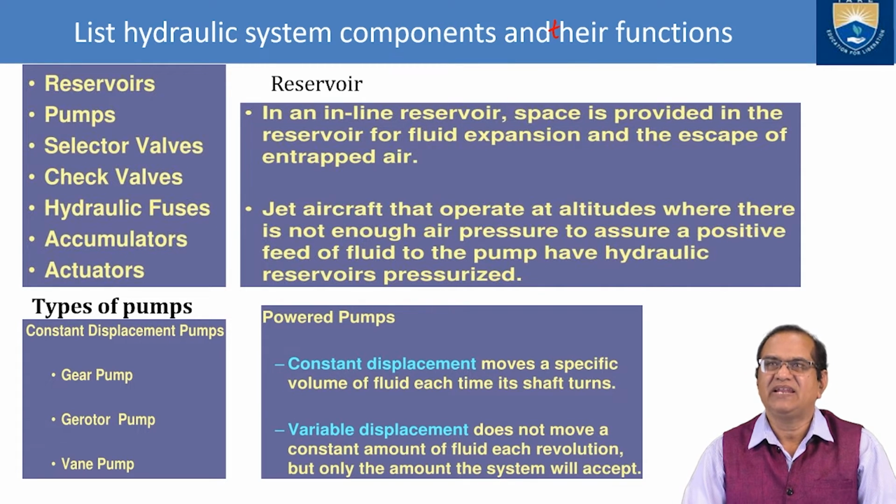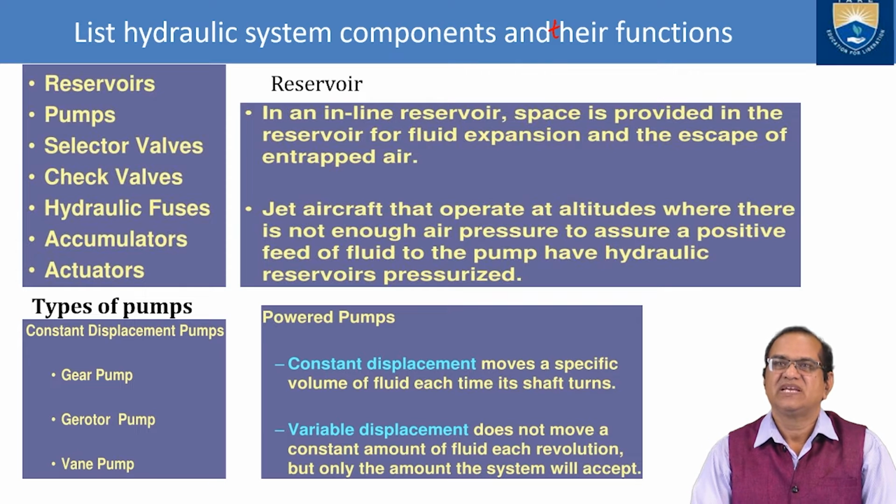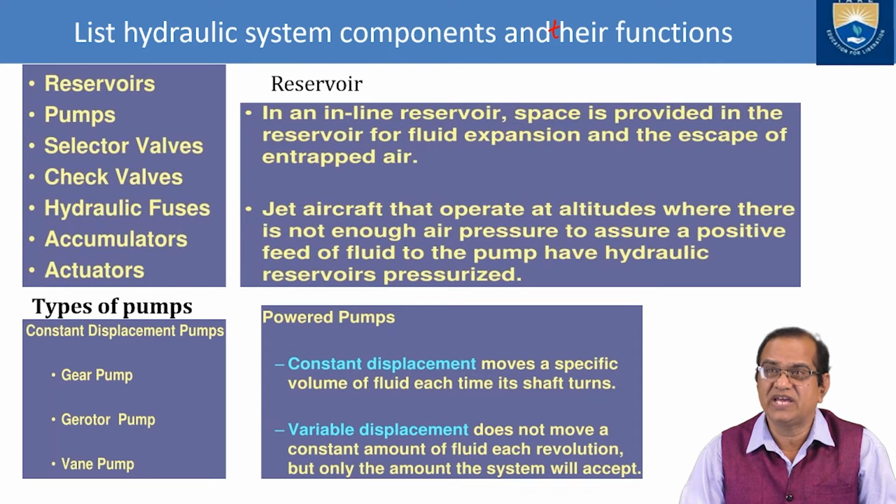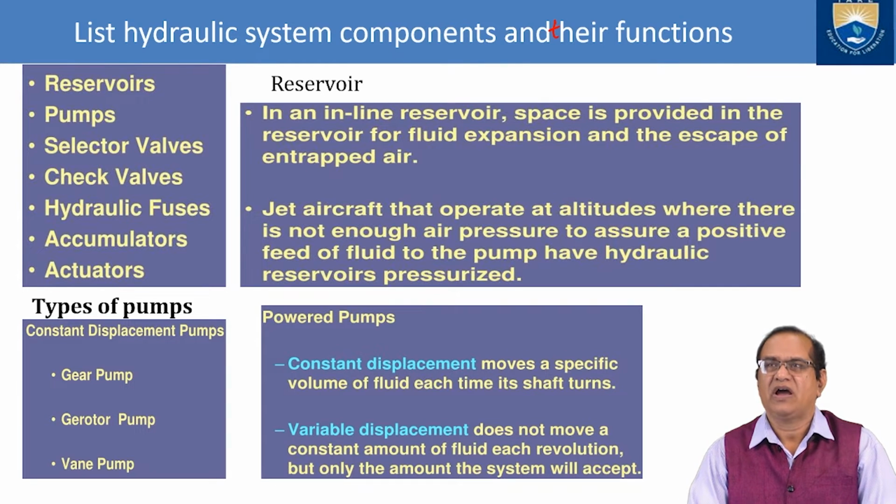In an inline reservoir, space is provided in the reservoir for fluid expansion and the escape of entrapped air. Jet aircraft that operate at altitude, where there is not enough air pressure to assure a positive feed of the fluid to the pump, have a pressurized hydraulic reservoir.